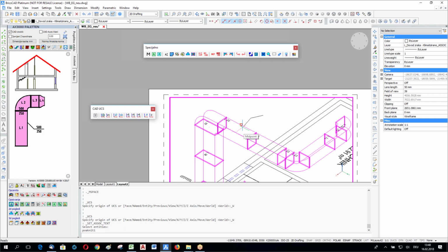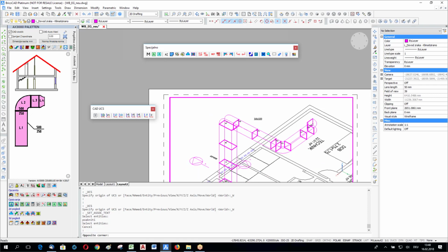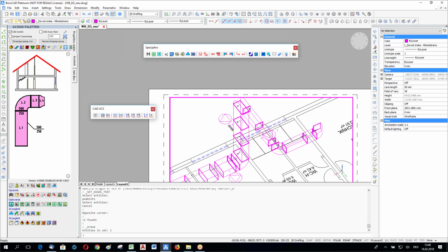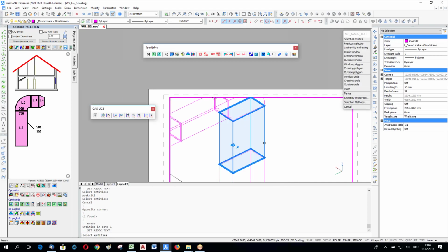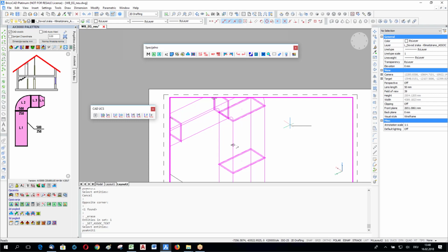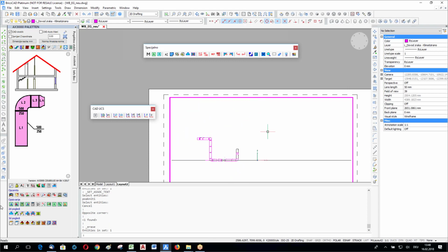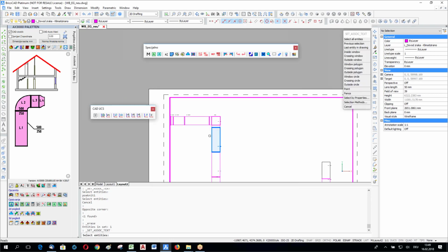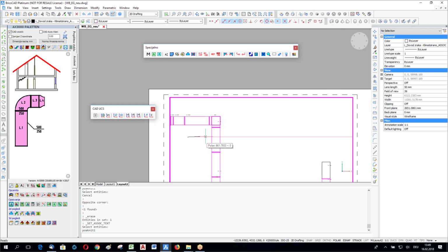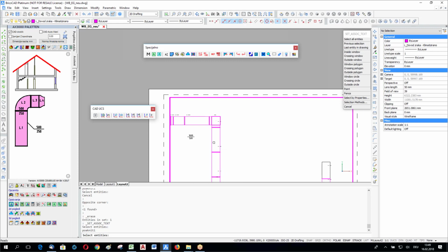You can see I'm using a polar function, for example, to label the ducts exactly in the position. If I change the rotation, maybe I only rotate to another side, maybe like this, and I use associated labeling, the same label, this element, is also rotated in the same direction. You only have to move it with polar to have it straight, so it's automatically calculated to the view. And the same happens if you look, for example, from the front, and the same is for the section. Associated labeling, maybe now I use another one, this one, first element. You can see it's rotated to the left. It's also rotated automatically.